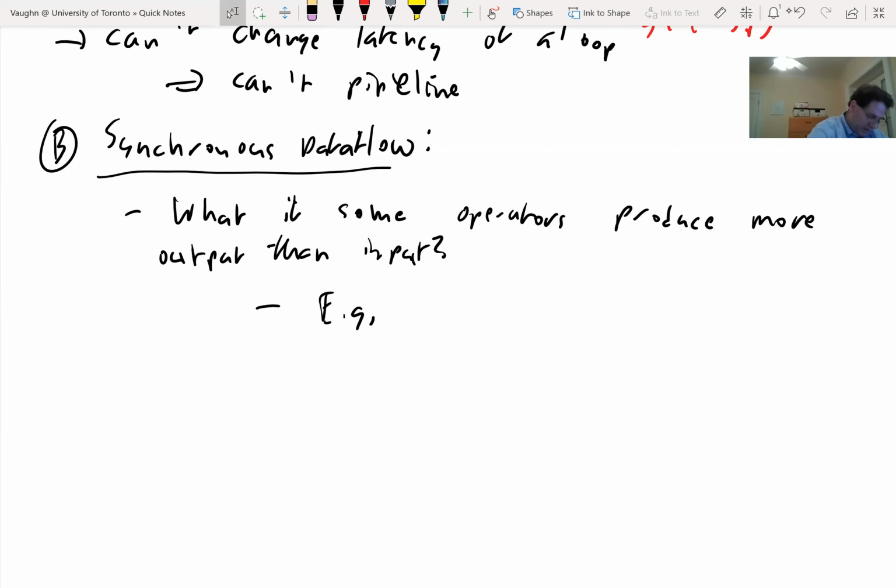So if I go to filtering again, because that's a very important application of FPGAs, you can have something called an interpolation filter. It's commonly used in various signal processing and communications applications. An interpolation filter, basically, data comes in at a certain rate and you fill in the gaps. So maybe data comes in at 100 megasamples per second and you interpolate to take that up to 200 megasamples per second where you filled in intermediate values. And that turns out to be useful for some of the downstream signal processing.